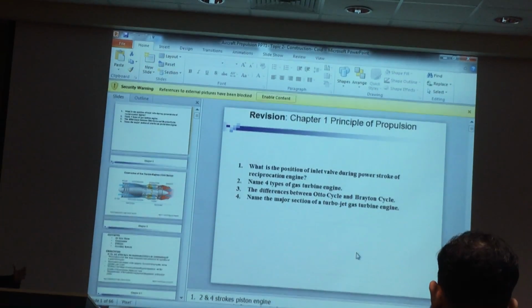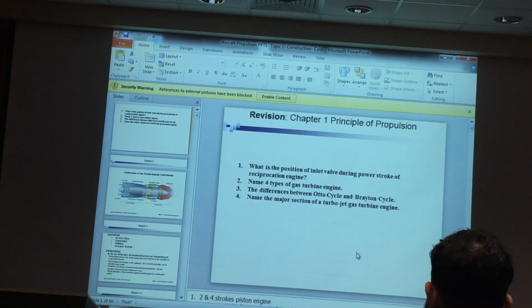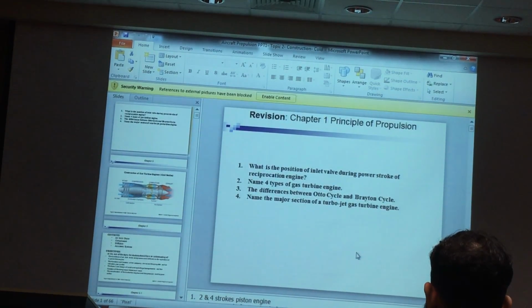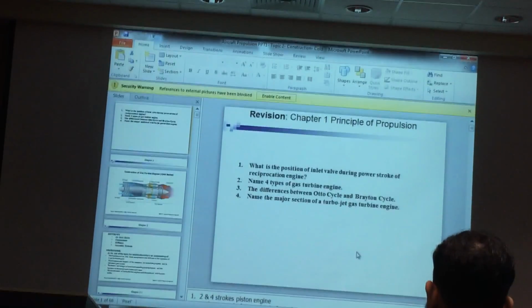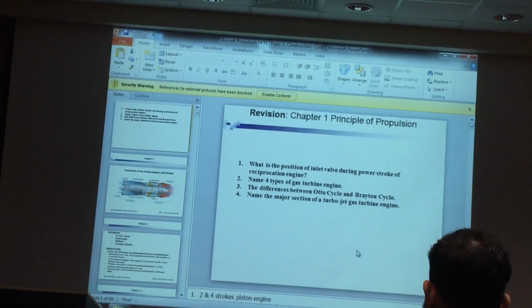So after the intake comes the low pressure compressor, then the high pressure compressor. Next after the compressor is the diffuser. The diffuser is just empty, divergent space. It increases the volume to give you higher pressure and slows down the velocity a bit, stabilizing the airflow. And then is your combustion chamber, with the nozzle and ignition. The nozzle is to atomize the fuel, not to burn the fuel. The burning takes place in the combustion chamber.